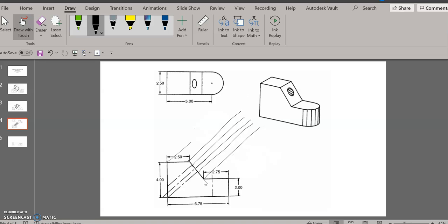And I'm going to go ahead and include these surfaces as well. Okay? All right, the next step is I need to draw a vertical line in orientation to the auxiliary view. That way I can go ahead and start with the thickness of my surface. And I'm going to approximate, here it says 2.5. I'm going to approximate that here on my auxiliary view there.